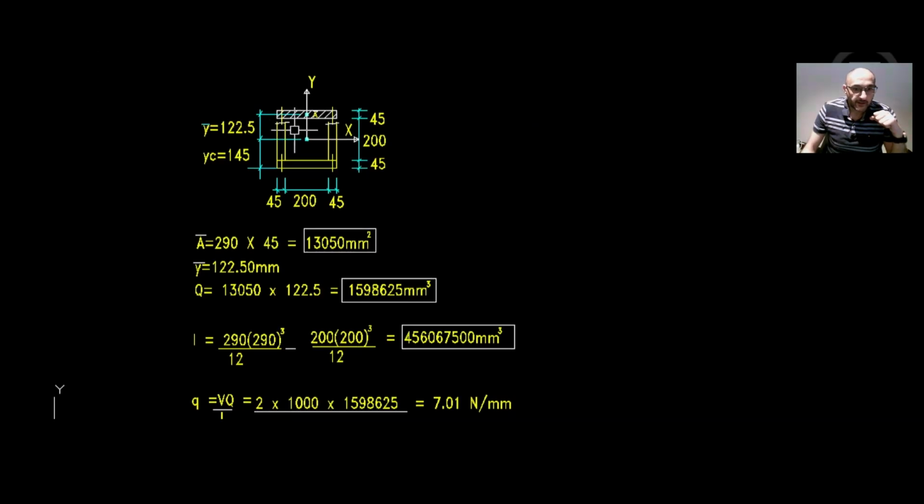Right, here we have fixings F1, and they're all the same around this corner of this box section. Now what we need to do is, at the fixings, we will shear right through the cross section through the fixings. So how many shear do we have? We have 1 shear that's going right through the fixings. And when we shear, we need to shear right through the cross section throughout the entire beam. Okay, this is the idea.